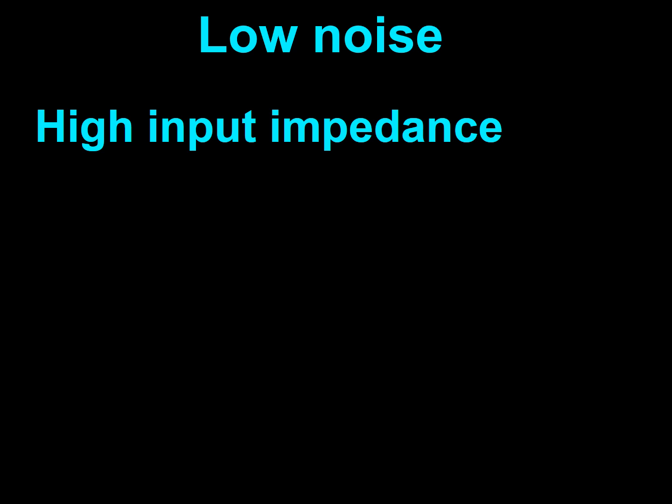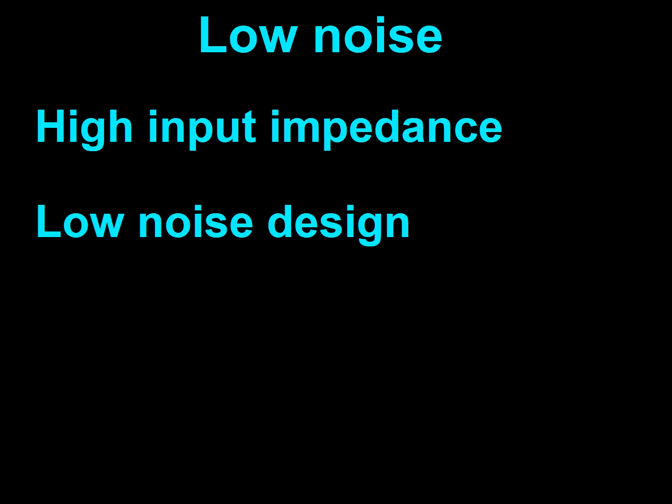Noise can be defined as any unwanted signal, that is, any element that, if expressed in the EEG tracing, is considered an artifact. The way amplifiers can help to eliminate artifacts are by having a high input impedance, by having built-in components that themselves produce little noise.